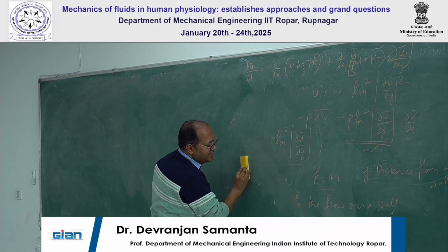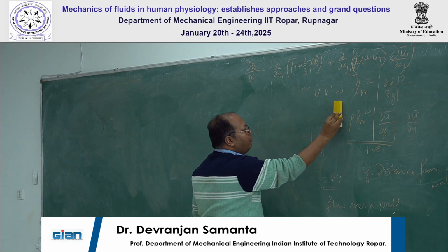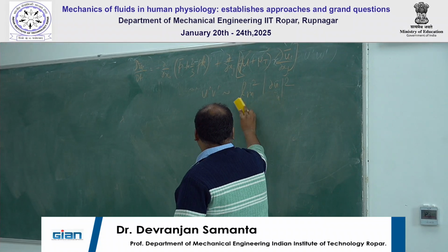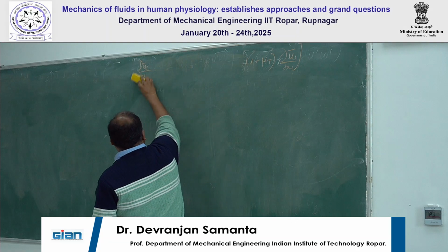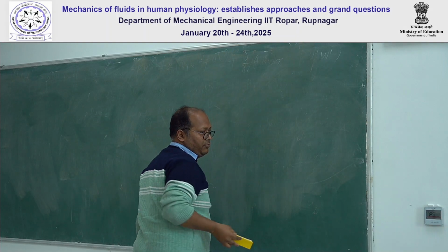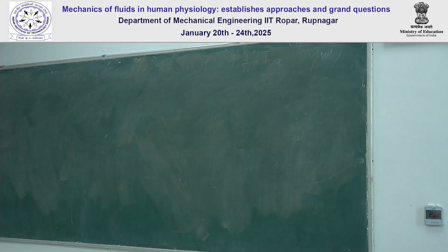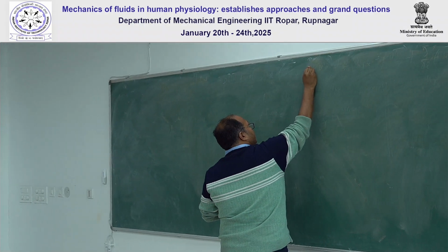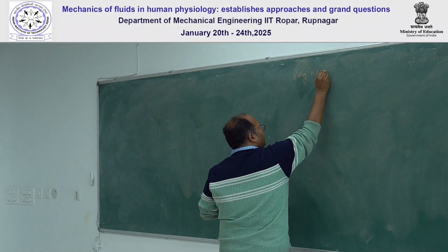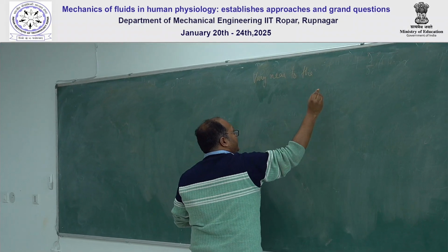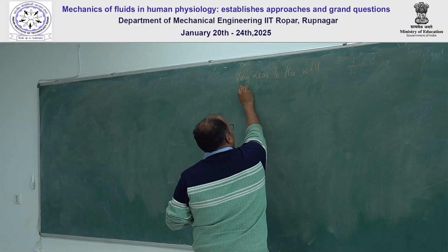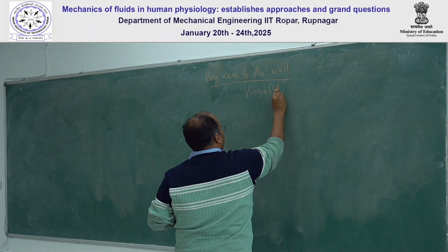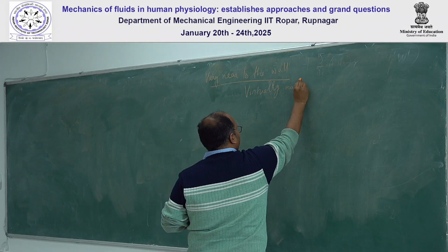So we will not consider the Reynolds stress component, only the mean velocity gradient, when characterizing the shear stress very near to the wall. Virtually no Reynolds stress.